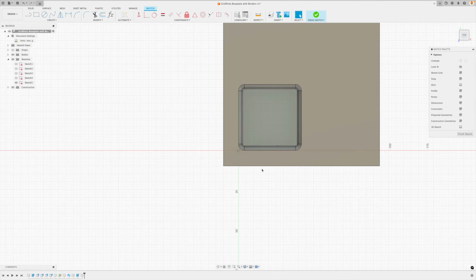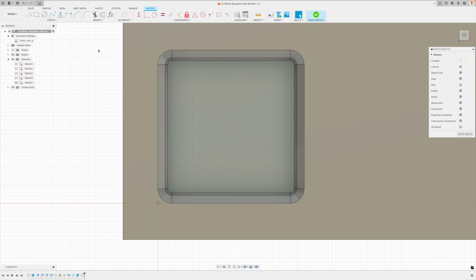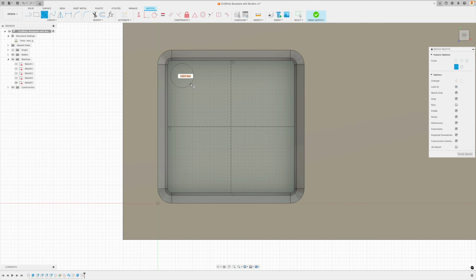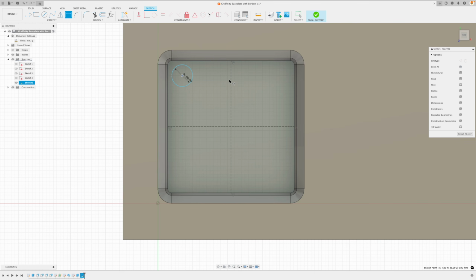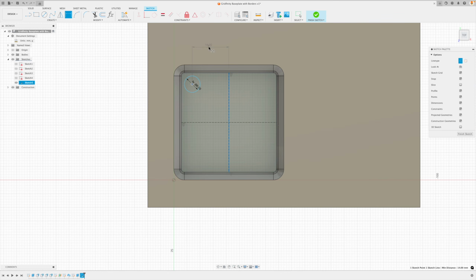Next, we're going to create a sketch on this face. Let's do that. Create sketch. And it inherits all this geometry as well. So we can work with that. For example, it will find the midpoint. Let's put a line from midpoint to midpoint and do the same thing over there. And in fact, I'm going to press X on these lines to turn them into construction lines. Next, our center diameter circle. We could do the math right here, but I would like to just put in our magnet diameter. And then the math, if we calculate it correctly in the design reference, all we need to do is pick the center point to our center line, and this is going to be 13 millimeters. And we'll do the same thing over here, 13 to 13, just like that.